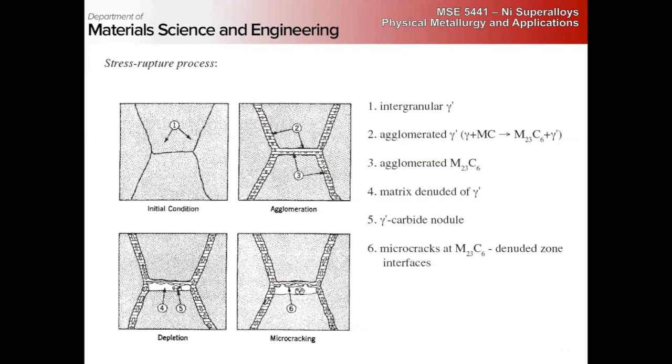You've got all these disks rotating, moving between vanes, and you want to minimize the amount of losses due to aerodynamic forces. That means the tolerances in there are really close. In fact, a lot of engines have something Pratt & Whitney calls turbo tip, which is essentially sand glued to the top of the turbine disk so that when it starts up, there's clearance.